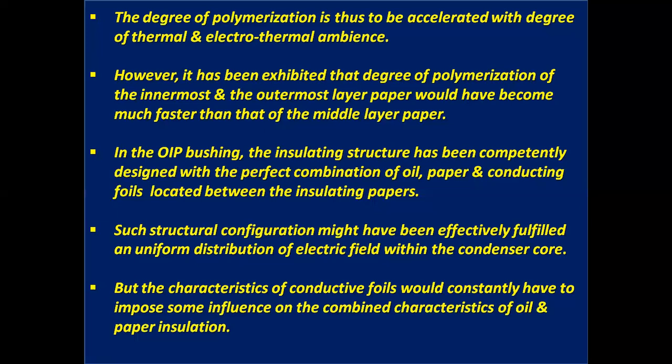In the OIP bushing, the insulating structure has been competently designed with the perfect combination of oil, paper, and conducting foils located between the insulating papers.